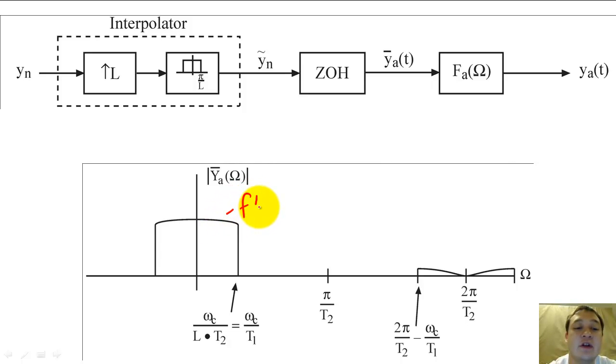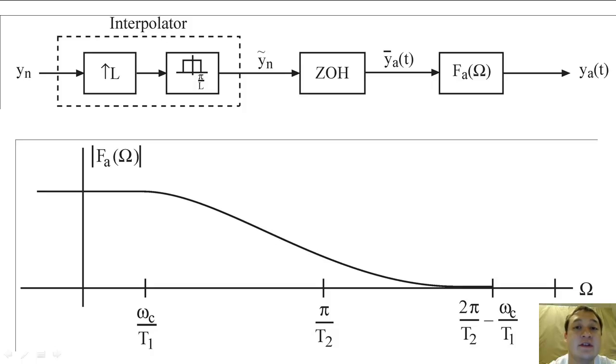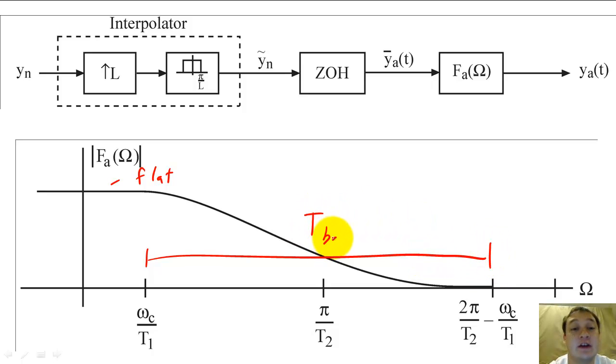Therefore, the low-pass filter does not need to emphasize the higher frequencies as much, so the passband of the filter can be more or less flat. This again simplifies the analog circuit. In addition, since y_d is narrower, the low-pass filter's transition band can be significantly wider. Since the transition band is wider, we ultimately create a cheap, low-power analog filter.